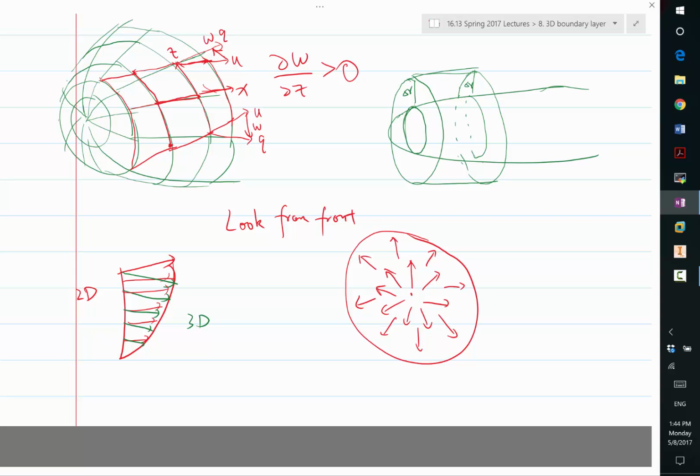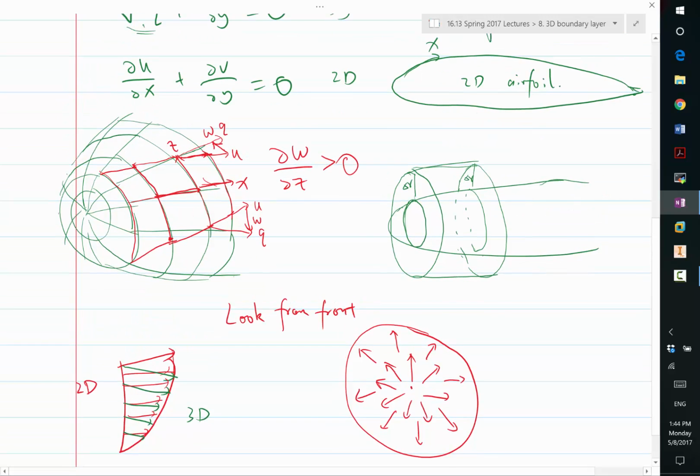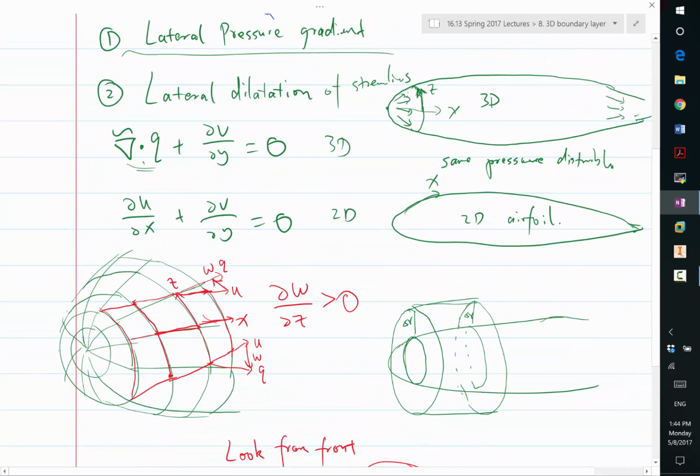But if you have convergence in the lateral direction, like at the trailing edge, the effect is opposite, right? Because in the third dimension, the flow converges, that has the effect of pushing the flow outward. Think of a tornado: if you have streamlines converging to the same spot, the only place the flow can go is upwards.